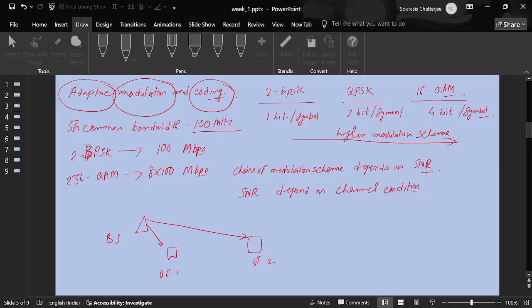Adding redundant bits, putting redundant parity bits. Okay, you want to introduce parity bits. I guess you are referring to the scenario when you have a certain number of message bits and you are going to introduce a certain number of parity bits, depending on your rate. So how does it really work? For example, if I consider a scenario where I would like to introduce one parity bit per three message bits.